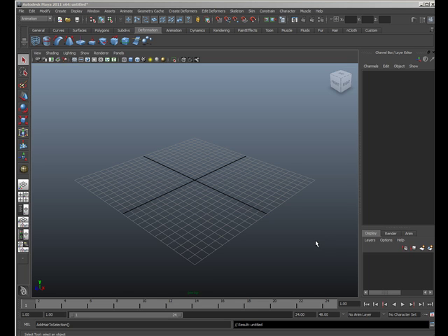Hair.Basic allows you to utilize existing polygon tools inside Maya for creating and modeling hair. It contains tools for generating hair strands from geometry parametrically, following the geometry contours as it deforms, and then translating these hairs back to geometry for rendering.